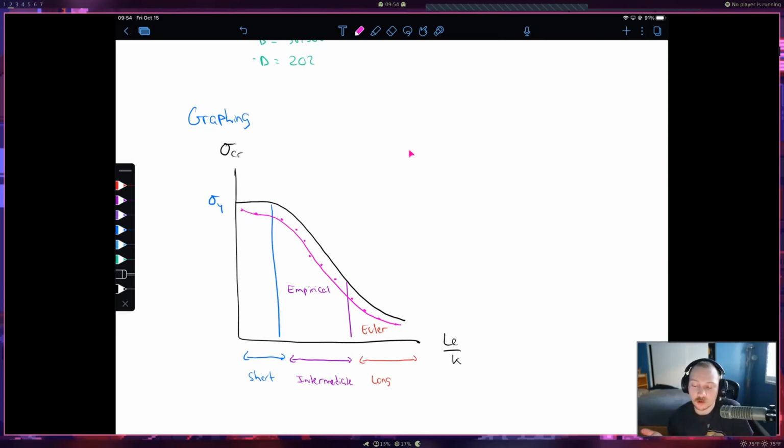If we have a short column, we're going to use intervals of loading of 75 pounds. So you're going to start from, of course, 0, use the thumb wheel, go up to 75 pounds, and keep going in those intervals until you reach your critical load, where, remember, right after that critical load, the column is going to fail. Basically you'll see that you can't apply any more load. That implies that it failed.